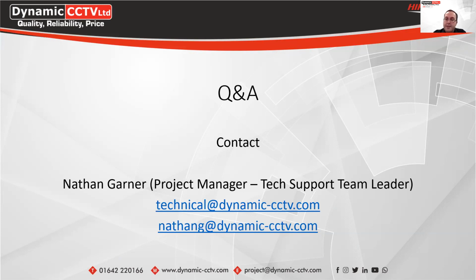Peter's also asked, please can you explain the filtering time again on ColorVu and IR? Does this affect reading of number plates on vehicles? The filtering time doesn't affect being able to see license plates on a nighttime image. For standard IR cameras, that would be the exposure settings.